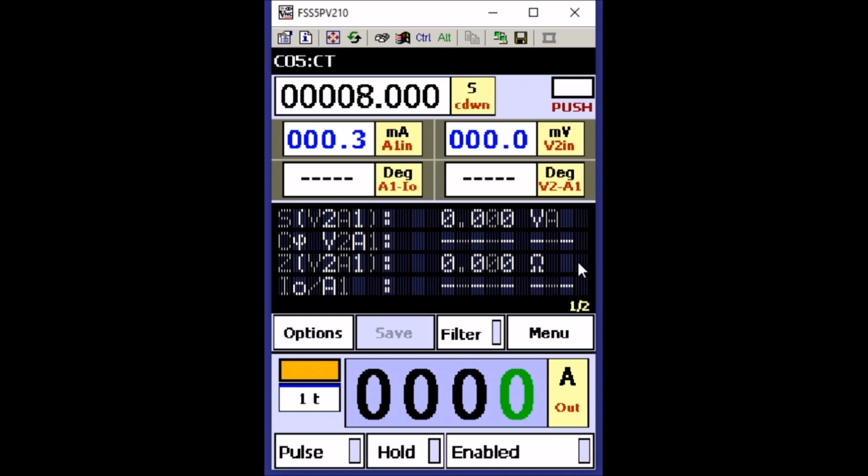In this particular template, we will get apparent power, which is the product between the measured voltage and the measured current in the secondary. In this case, we are not measuring any voltage because we don't have any voltage drop at the secondary. We don't have any burden connected. This is the phi cosine, the cosine of the phi angle. We don't have any in this case, also because we don't have any burden. No angle will be produced at the output of the secondary.